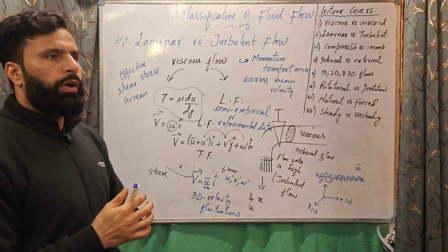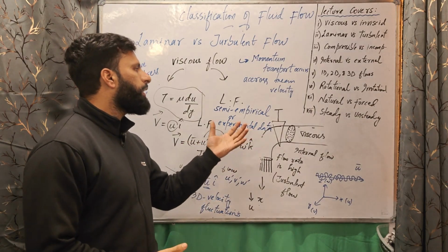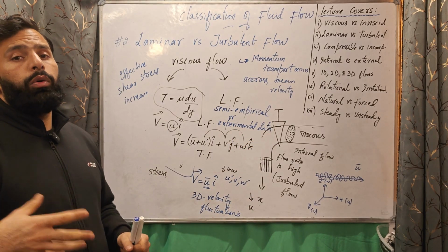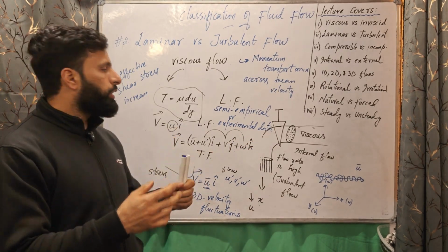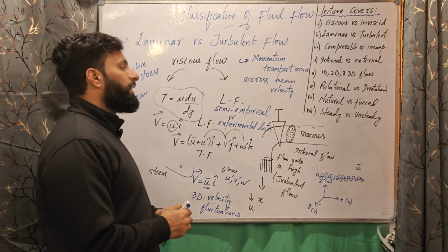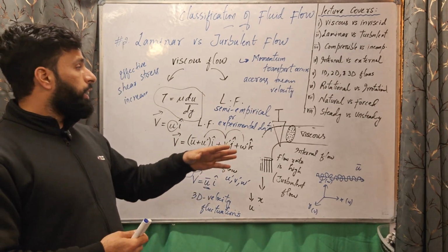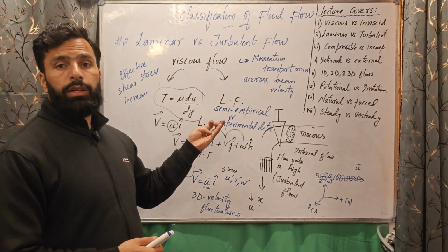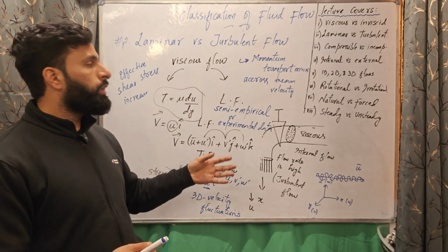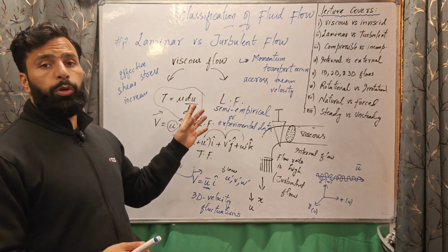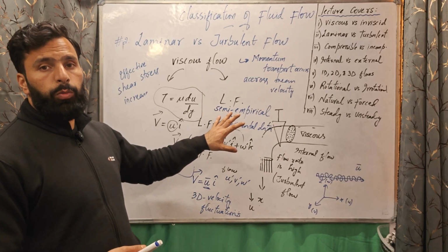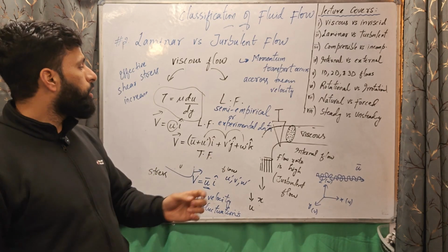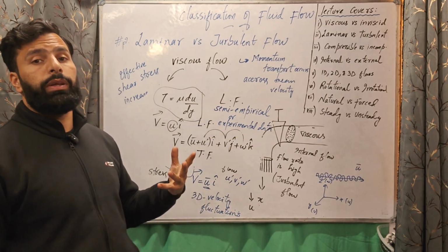In case of turbulent flow, either we go for experimentation, using purely experimental data to predict something, or at most we can combine the theory and experimental data to generate equations which are not fully developed from theory, using the basic laws of physics like the conservation of mass, conservation of energy, and conservation of momentum principles. Those would be equations developed purely from theory. That is not the case for turbulent flow. So for turbulent flow, we combine the theory and the experimental results to develop the equations. We call them semi-empirical models or semi-empirical relations.